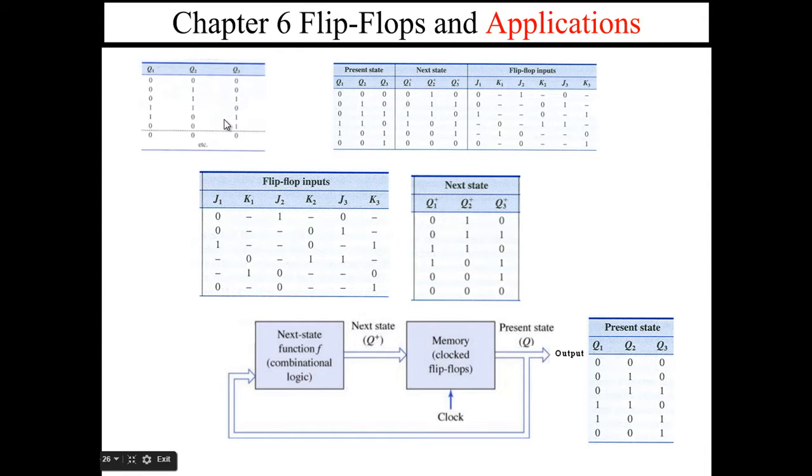So here's our desired output. We can see that reflected here in our present state. Our next state drives us in a zigzag fashion when the clock ticks down to this row. So the Q plus state never really exists, but we think of it as existing inside the setup. So these JKs set up these next Qs. So when these are present in the wires here, these 6 wires, this arrow represents 6 wires in this particular circuit, they're going to cause this to happen when the clock hits. And then immediately when the clock hits, this is going to be our output. So if we were at a 0, 0, then we're going to go to a 0, 1, 0.